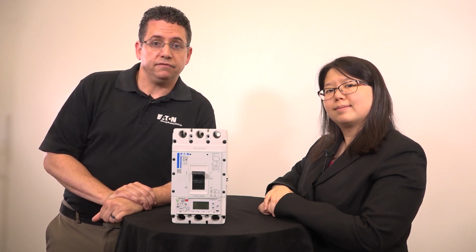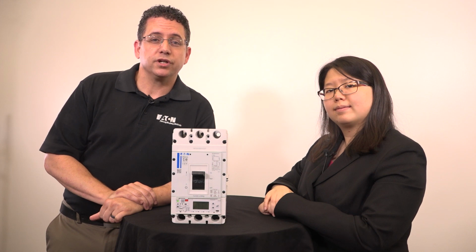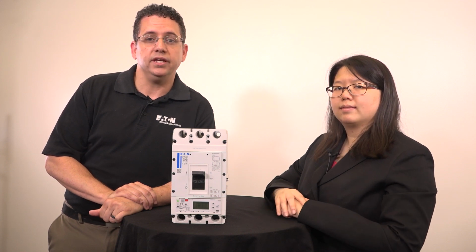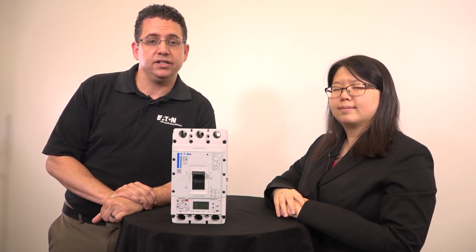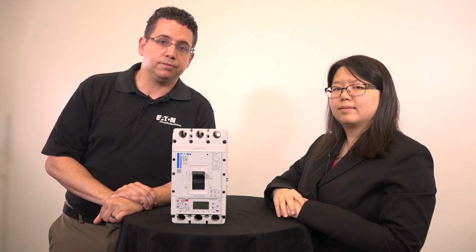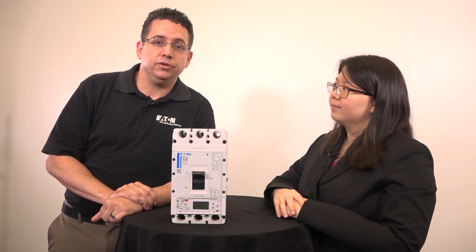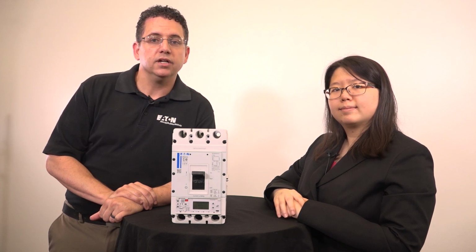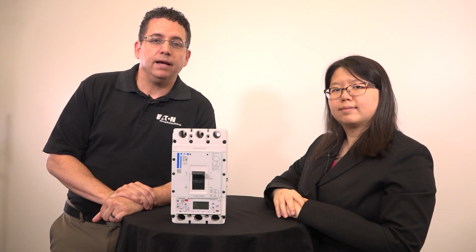It protects the cables and the devices you have downstream because if you're continually overloading and tripping your breaker, that's probably a load or system fault that needs to be corrected before the insulation on the cables gets so hot they start to melt. Here's the problem though. Electronic trip units normally don't behave that way. After an electronic unit trips and opens the breaker, the trip unit may lose power and forget that it was overloaded. And the cables are hot.